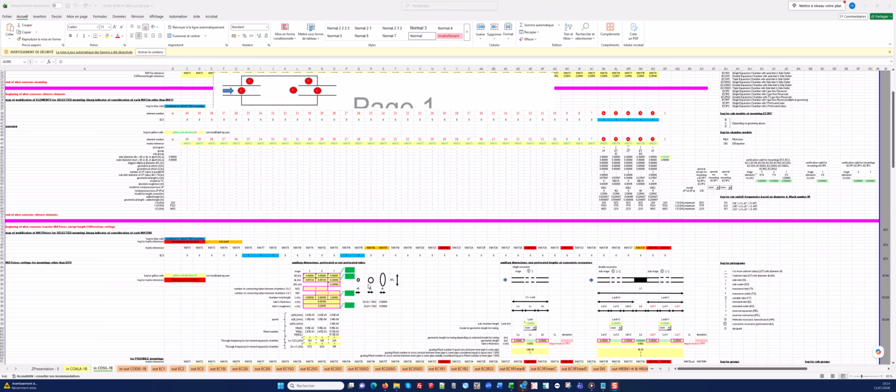In case of circular cross-section, ds is the smallest diameter, dl is the larger diameter, and we can enter here for the stage 1, 0.1, which is entered by default, for the smallest diameter, 0.3 for the biggest diameter, 1.2 meter for the chamber total length, and 1.5 minus 4 for the tube's roughness, which is a usual value set by default.